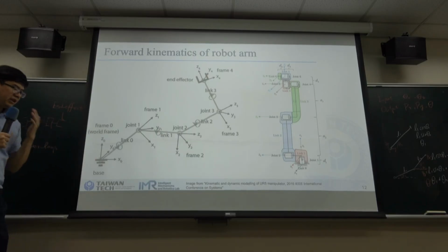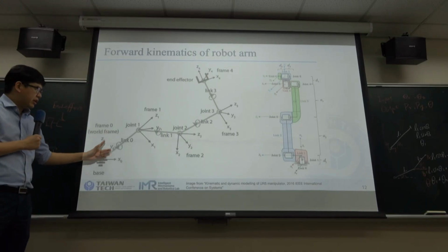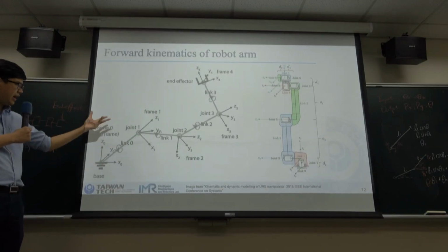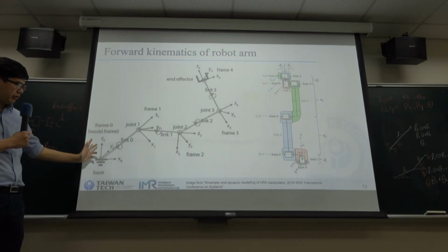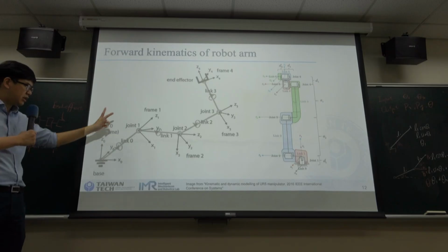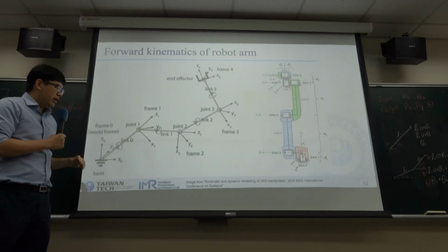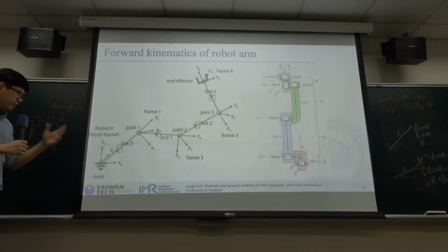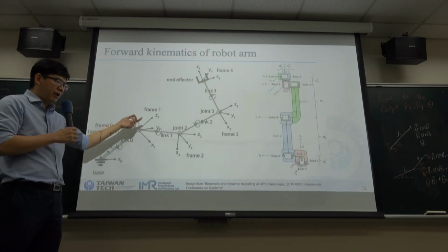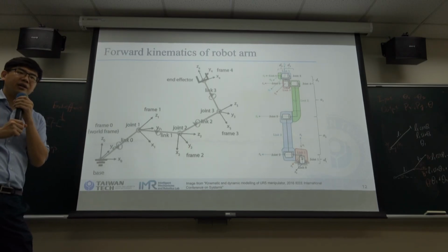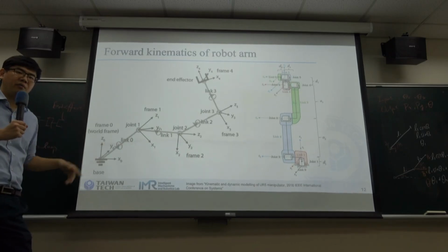And I know this is quite difficult. You want to make sure what is the orientation when you rotate about X, and rotate about Z. So after setting up these frames, you will need to write down the correct homogeneous transformation matrix, if you still can recall from last week, our homework.